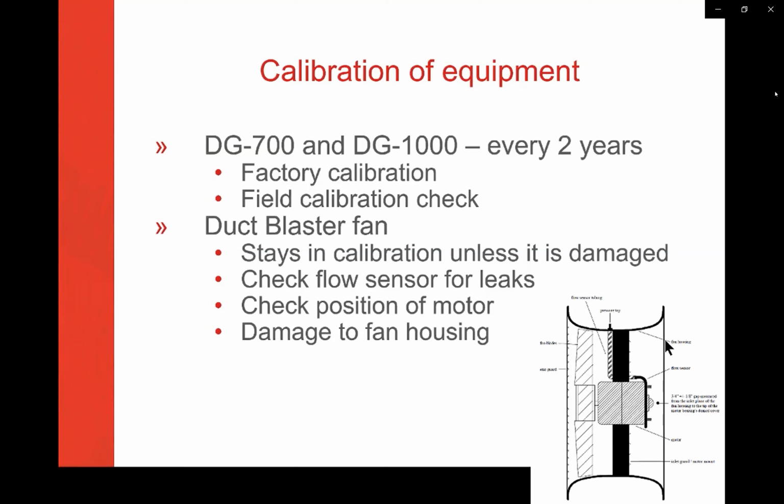The position of the motor and the position of the flow sensor matters. There's a couple of bolts that are holding that flow sensor in place, and you can tweak the reading of the fan a little bit by moving that flow sensor in or out a little bit. So if that's been moved, that can be adjusted. And if there's any damage to the fan housing, where there are holes in the black fan housing, that is also going to affect your readings.